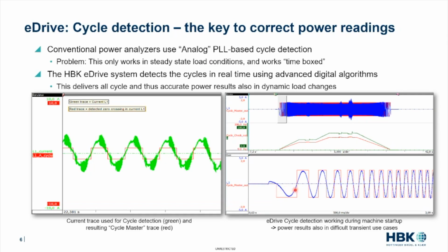A traditional power analyzer will need at least a few cycles until it can drag its analog PLL to that frequency, and it will probably give you a reading back here, the first reading, and you will be completely blind at the startup. So that's one important point that we can measure at startup.